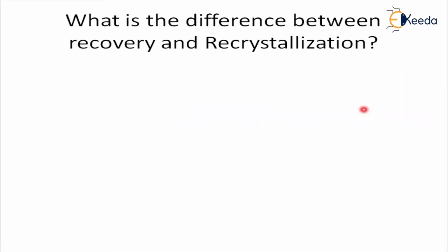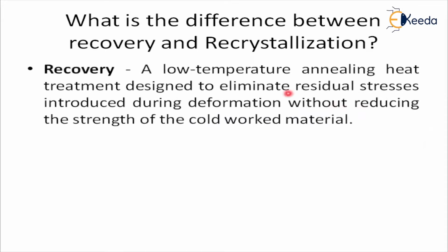And what is the main difference between recovery and recrystallization? First of all, observe the recovery here. So here the recovery is observed at low temperature. That means a low temperature annealing heat treatment. So means recovery is an annealing process, which is a heat treatment process observed at low temperature, and the main purpose is to eliminate residual stresses during deformation.